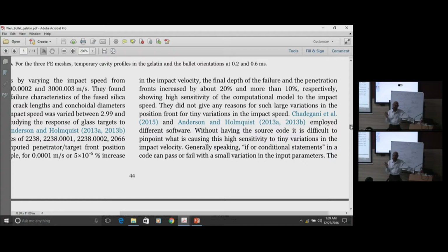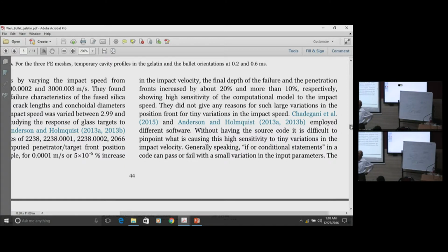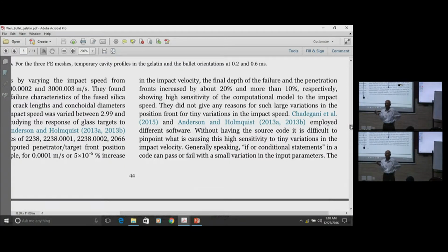With our code, with Abaqus, we did not see that. Now, whether it's because the student's mesh was not very fine, I cannot answer that question. Or the crack length we were measuring, we were not measuring correctly because we were deleting elements. I have not talked about that, but I will. So we were deleting elements, failed elements were deleted. So basically the minimum crack width was the width of an element, and the minimum crack length extension was the element length. So whether we missed something there, we did not see that much effect.